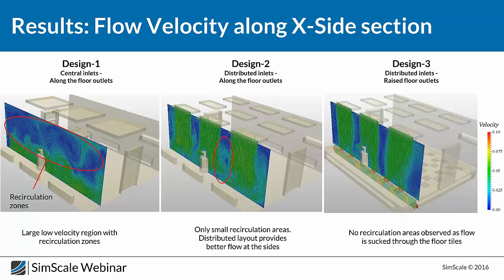So this is interesting because when the particles enter the room from this contamination source, the flow pattern on this plane is very influential on how they're going to be distributed. So let's have a look at these three snapshots closely, because in a later slide we will see how these flow patterns really affected the distribution of the contamination.